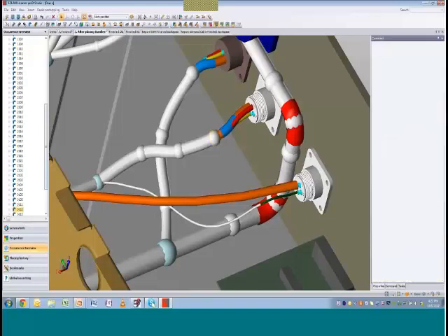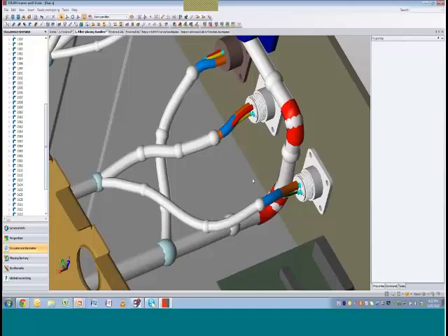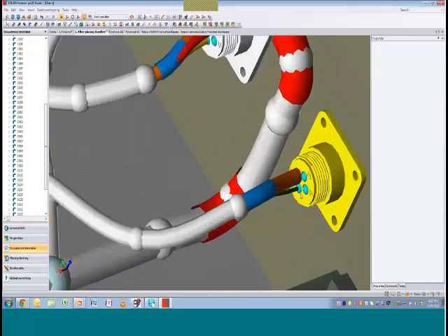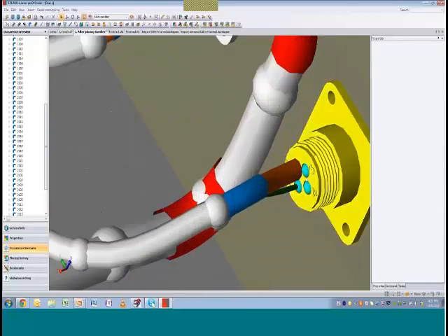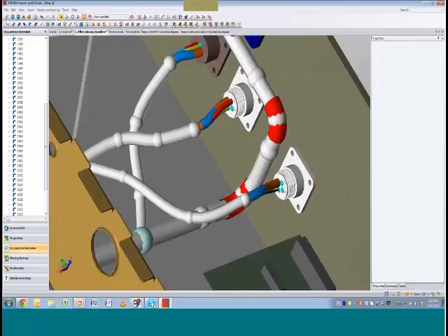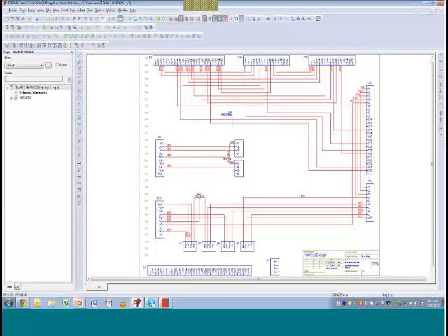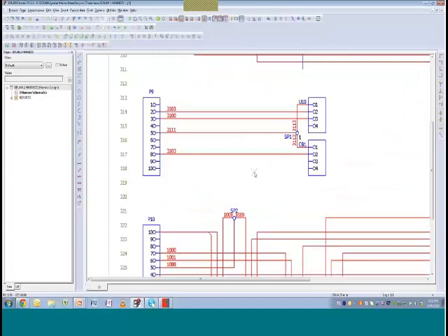So now we want to go ahead and bring in some new wires. Here you can see we have a couple of pins that haven't been associated yet. We have pin 3 and pin 4. Currently they don't have any wires assigned. But if we were back in our electrical project, here on CB1 I have pins 3 and 4 that are available. If we go in and add a couple of wires,